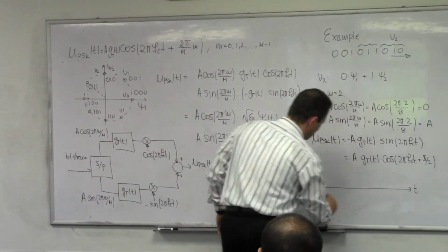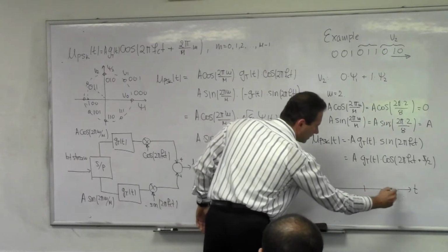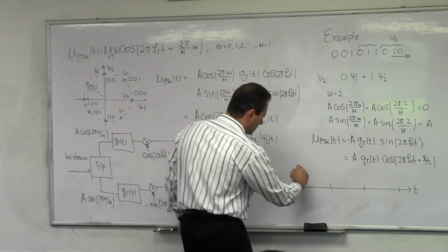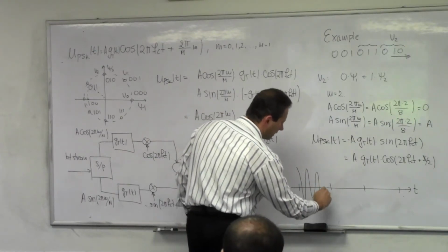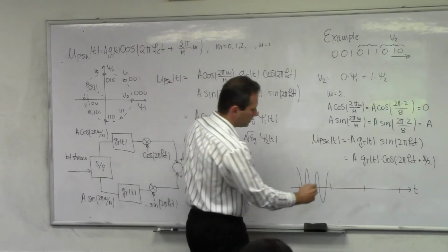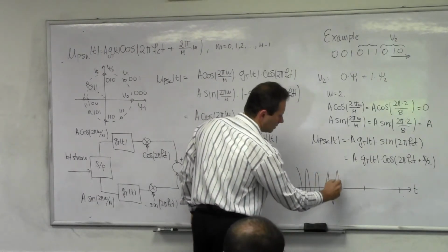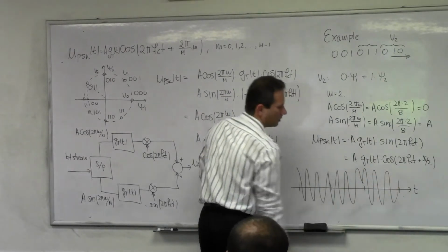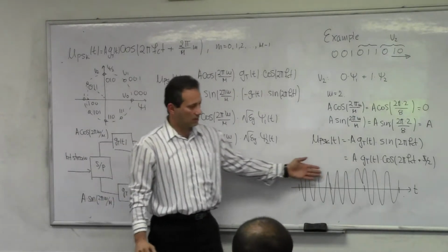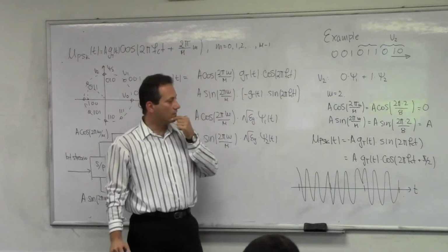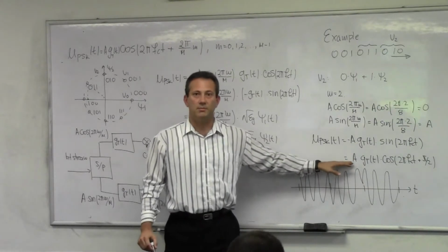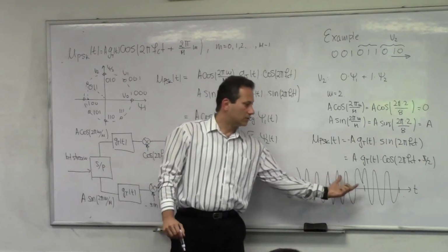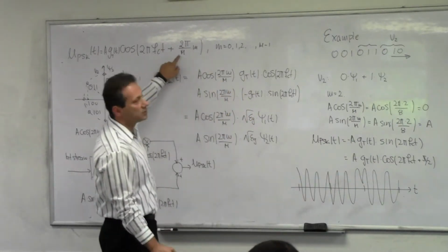You can think of this as your signaling intervals, where you modulate 3 bits at a time. And here is, for example, one angle, and then you get to this boundary, and at this boundary the angle may change. Right? And at this boundary the angle changes again, and so on. So the receiver sees this essentially cosine waveform that always has the same energy, same power, right? Because the magnitude is always the same. But at the boundaries of your symbol interval, this phase here will change.